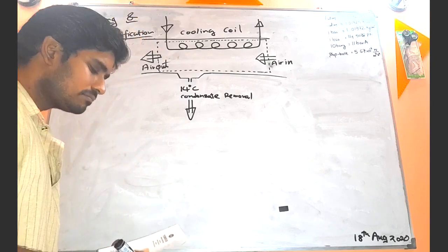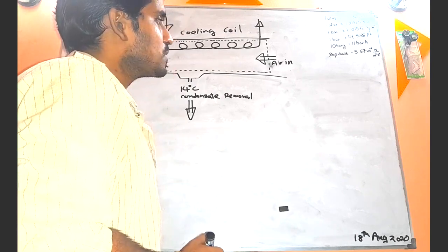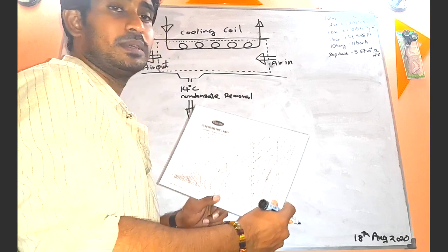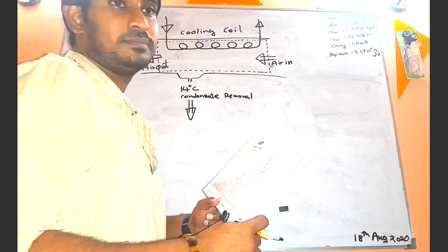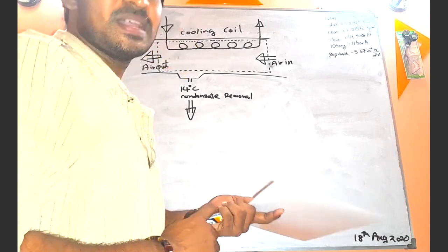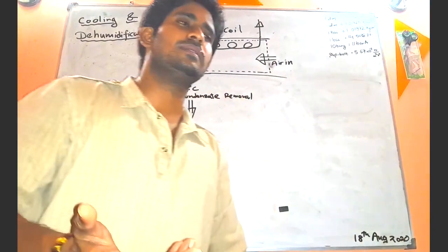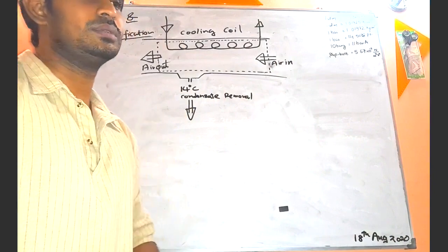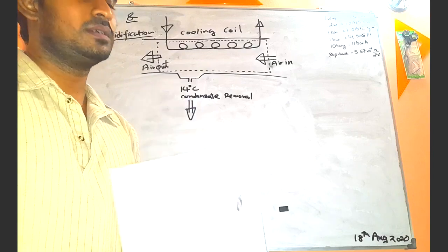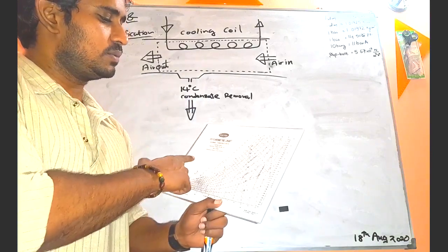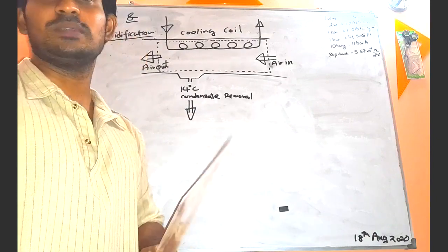Let's include the values that we have to obtain from the charts. We are going to use the psychrometric chart at sea level, because, as I told you even in the introduction video, when using the psychrometric chart it must be specified what the particular pressure is where the chart is made, which is the barometric pressure.